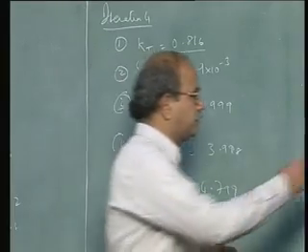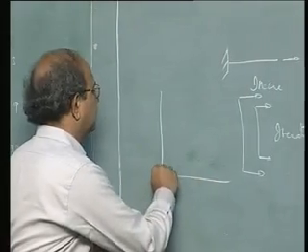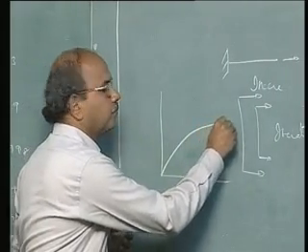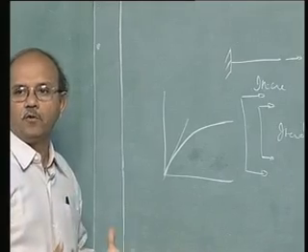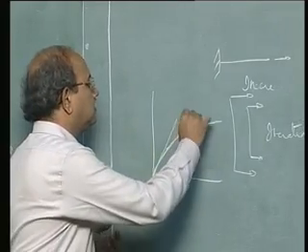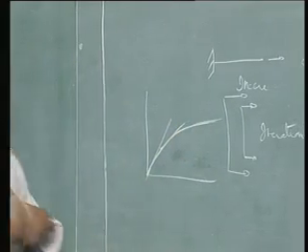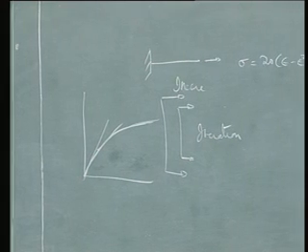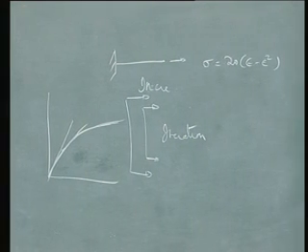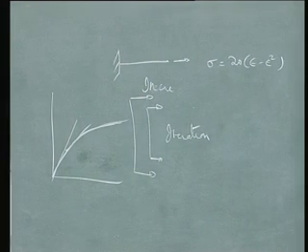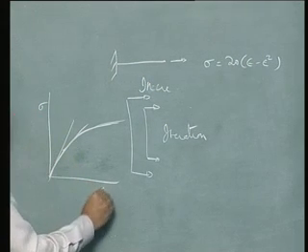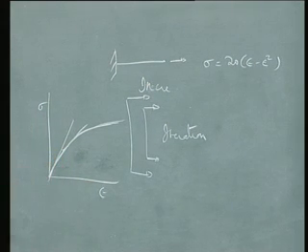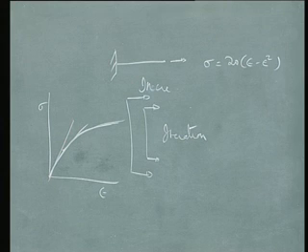In other words, what it physically means for this problem is that the slope of this curve, which is very nicely sitting here with the value of 4, is now dropping. So once it drops like that, obviously Kt, which depends upon this Et, of course you know the sigma versus epsilon, which depends upon the slope of this curve, is going to become smaller and smaller.